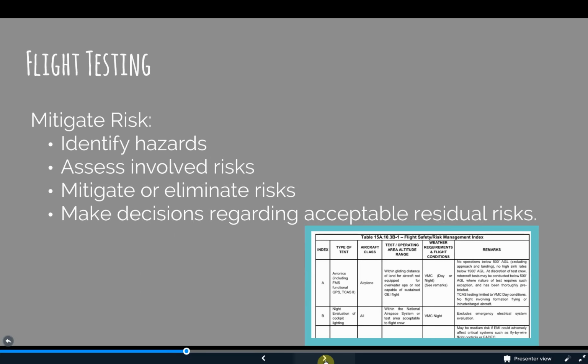When all of the required analysis and substantiation is complete, all the component and ground testing finished, the pre-TIA TCBM has convened, and the TIA has been issued, flight testing can begin. Order 8110.4 offers: for flight tests, the applicant performs the necessary tests and inspections and submits the results to the FAA for review. For certain flight tests, the FAA or the ODA may choose to conduct certification flight testing concurrently with the applicant. Due to the potential risk associated with flight testing, the FAA or ODA expects confirmation that the company was able to successfully complete higher risk tests before getting on the airplane.